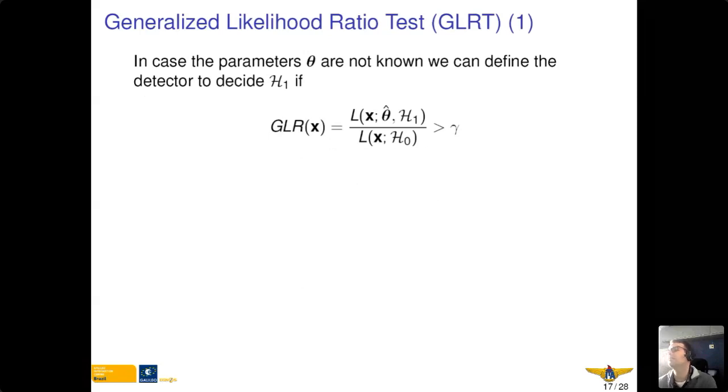We take an estimate of the parameters, and then compare the result based on the estimate with respect to the threshold. This now solves the problem of getting the initial estimates for our synchronization parameters, and on the other hand, detecting whether the satellite is present or not.